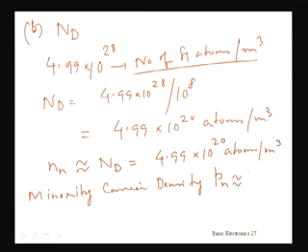So, minority carrier density, that is hole density, we have to find out, and we know from our previous discussion that Pn, the minority carrier density in n-type material, is Ni square divided by capital Nd. Now when you replace, you have to see, because Ni in our example is given, if you look into the problem, as 1.5 into 10 to the power 10 per cm cube. But here you see that Nd is per meter cube. So, we have to bring conformity by multiplying or dividing accordingly.